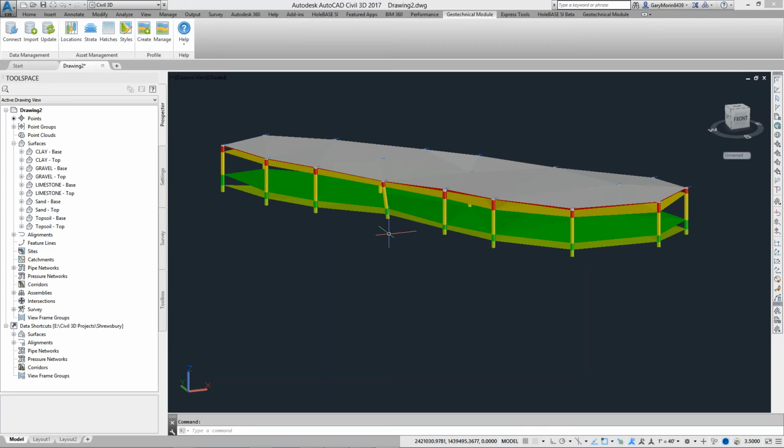I've got some nice data here, all nice, beautiful strata, each one nicely layered. In the real world, it doesn't always come in like this, so you need to use AutoCAD Civil commands like drawing feature lines and break lines and adding them to your surfaces. By doing that, you can actually model and caress your geology data so it actually looks and forms correctly. If you get a chance in a couple of minutes, I'll show you a little bit about how that works.